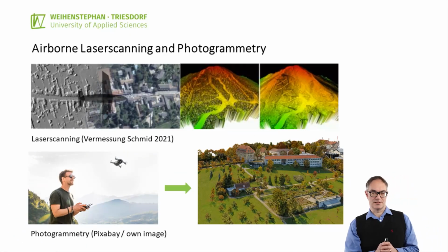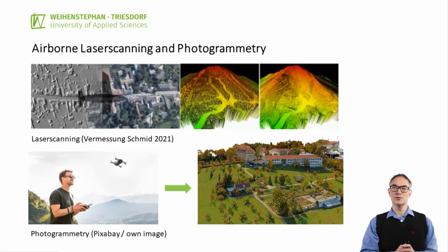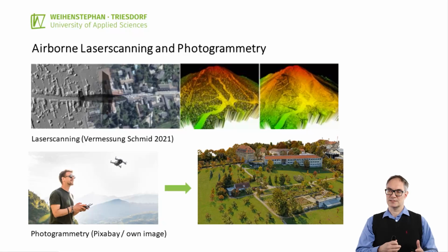Other ways to collect terrain data. We can use remote sensing. These are satellites, planes, or today drones to scan and survey our surface. First of all, these drones, for example, are just a flying tripod. But the key is in the sensor. And we have different sensors. We have RGB sensors, a camera, we have radar sensors, we have multispectral cameras, and we have laser scanning.